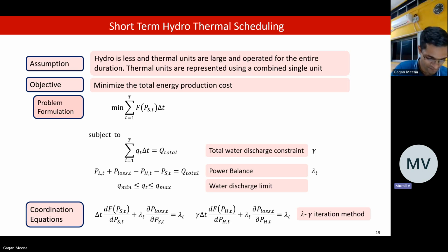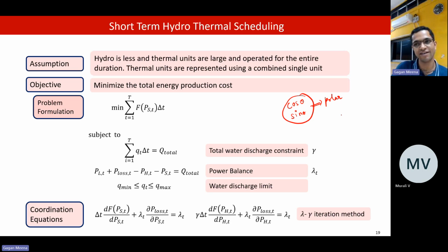The cosine and sine terms. Is that the only source? Yes, cosine and sine are non-linear functions, so that is correct. These two will come up only in the polar coordinate. Let's say if I use the rectangular coordinate, then I don't have these cos theta and sin theta, but the power flow is still non-linear. What is the other source of non-linearity?